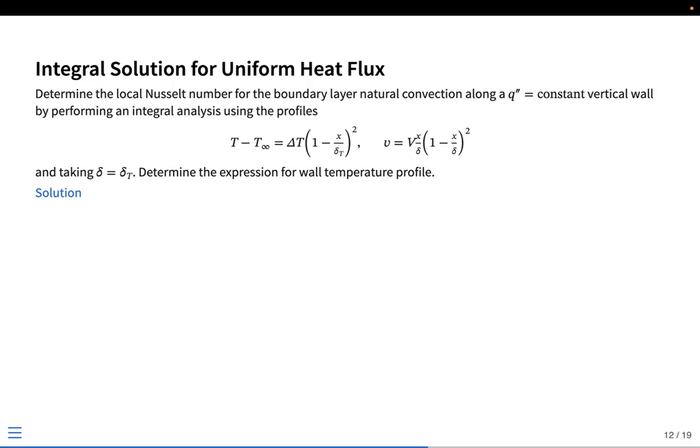So what would happen in this case is your temperature wouldn't be constant, as we discussed before, even when we were solving previously. Then you have a uniform heat flux and your wall temperature will increase as a function of y. To be precise, we have seen already that T_w will be proportional to y to the power 1/5. So wall temperature will keep on increasing as y increases.